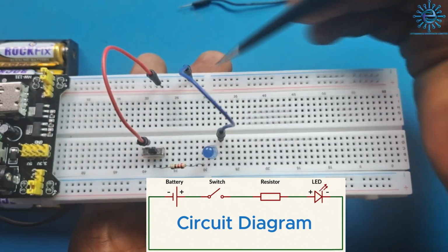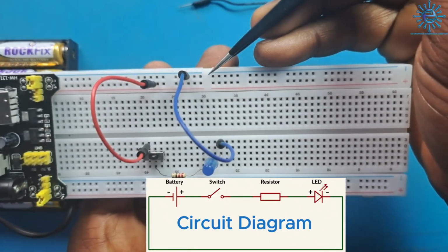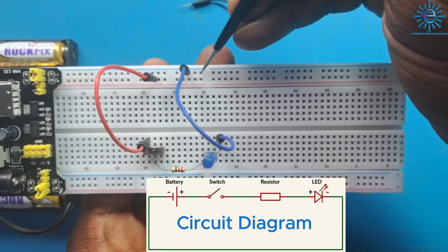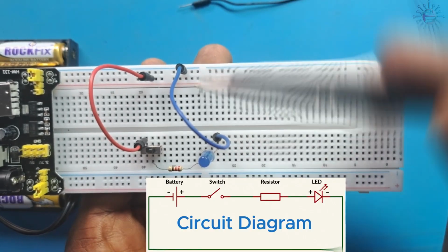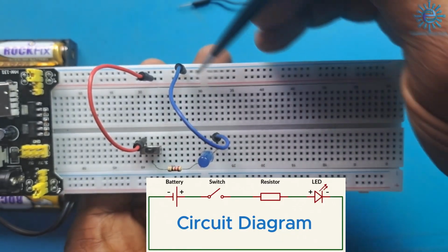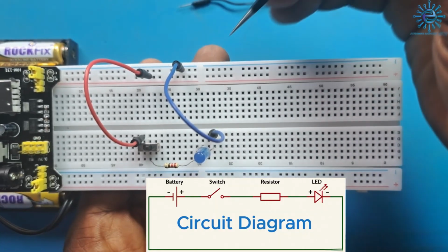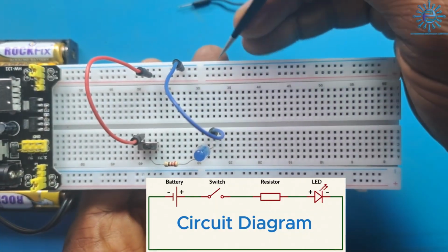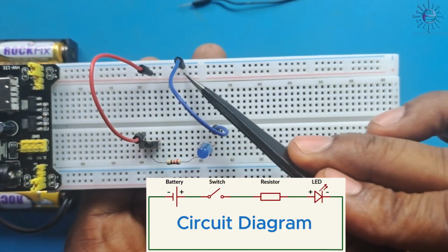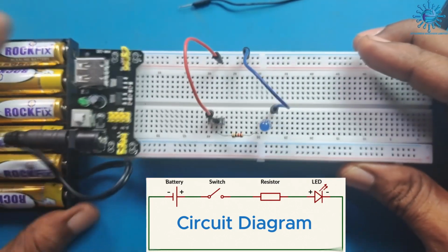Remember that on the breadboard we have a gap here. This gap shows that there's no continuity between this line and this line, and between this line and this line. For us to have continuity between this line and this line, we will use a jumper wire to loop from here to here. And also, we can use a jumper wire to loop from here to here. So far, our circuit is ready.